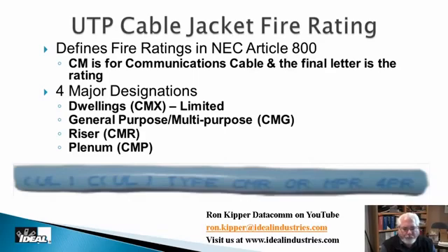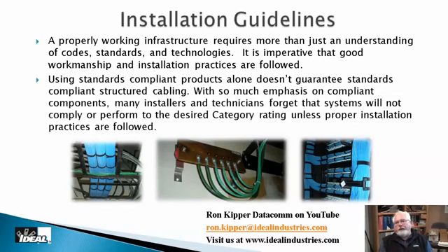Okay. Now, as far as installing cables in buildings, as a general rule, I'm going to tell you to try to be one of the last trades on a job, especially in residential. Commercial work, that's not going to happen. But if you're drilling holes and installing wires in a building and you have a large hole drilled and just a few cables passing through it, somebody coming in behind you can easily add their wires to that opening and maybe cause you some troubles.